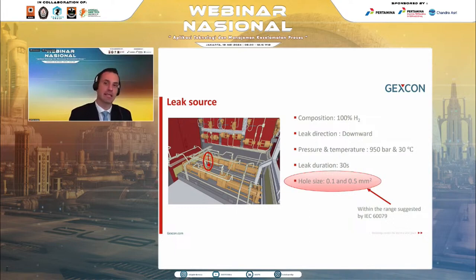Such high ventilation velocities needed to achieve high dilution for a non-hazardous zone or a zone 2 NE is just not achievable. It's more likely the 3-meter zone 2 would cover the whole enclosure, which is reasonable for a system such as this. But what could CFD modeling show us? Well, let's take a look at some of the results.